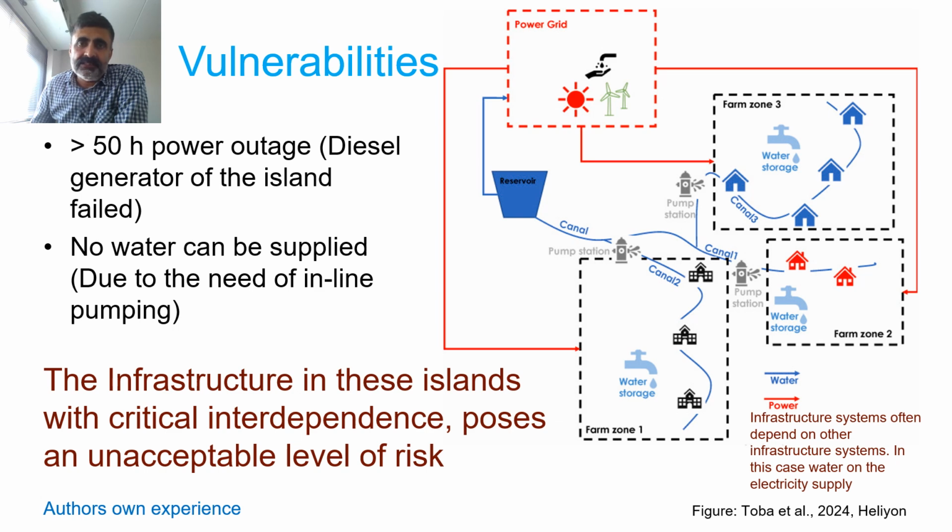But immediately, within minutes of the power failure, we observed that the water supply system had stopped. Due to the use of inline pumping as opposed to water towers which can feed the water under gravity, the water supply system stops functioning if the power supply is out.